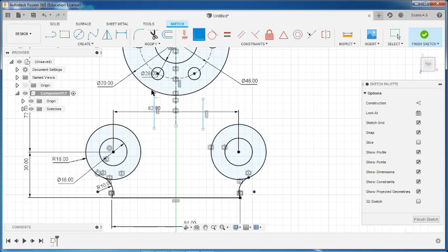This you can give coincident, this line is coincident here, this line is coincident here. Then give the value as 28. Then we will use symmetry, symmetry about this point, and this point is symmetrical about this.